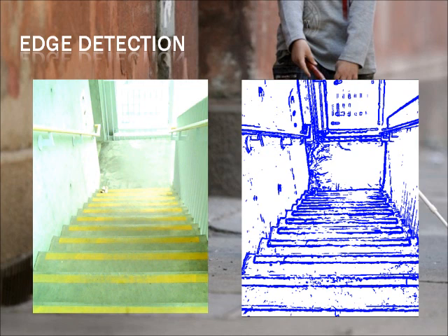After researching different algorithms, a hybrid of the Canny and Sobel edge detection algorithms was chosen. Firstly, the camera input is smoothed to reduce noise, and then the magnitude of the overall gradient is calculated. Where there's a large gradient, there's likely an edge.